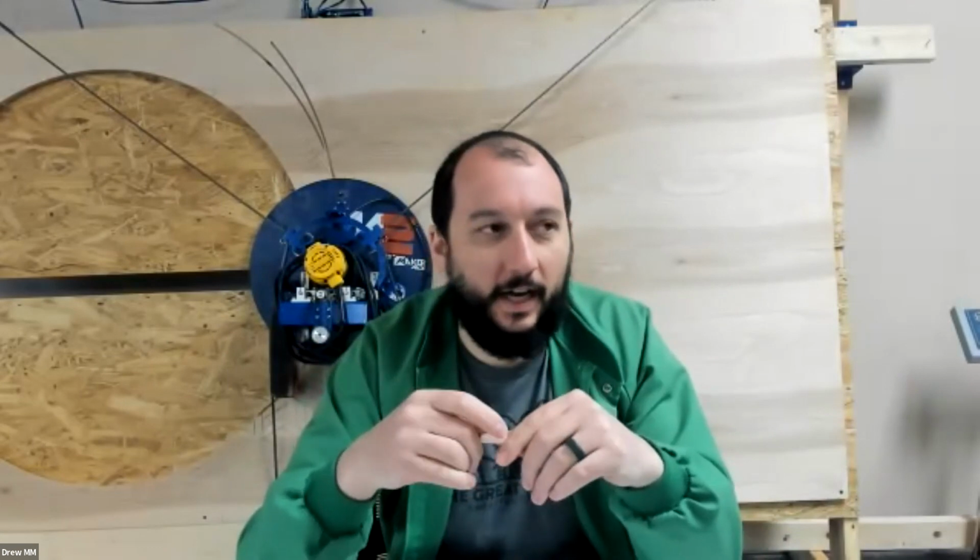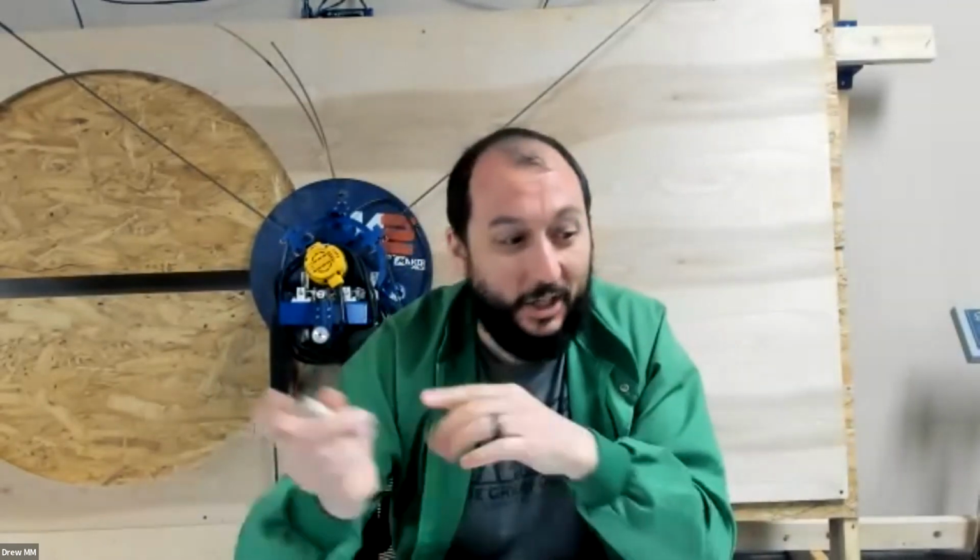It uses open source designs is what we started from, so a lot of the same parts that are out there, like an MK8 extruder and things like that. We print primarily out of PLA and PETG, the two things that we recommend. You can print in PVA, but it doesn't have a dual nozzle system. Even though it has a dual gate extruder, it doesn't have a dual extruder to print out of two nozzles. So if you wanted to print out of a material like PVA for a dissolvable support, you'd have to switch the filament in and out, and that would be a pretty big hassle.